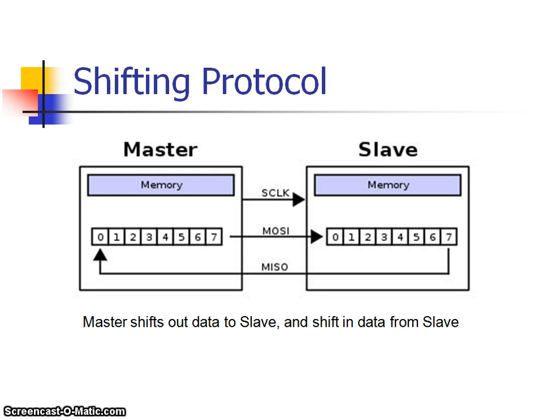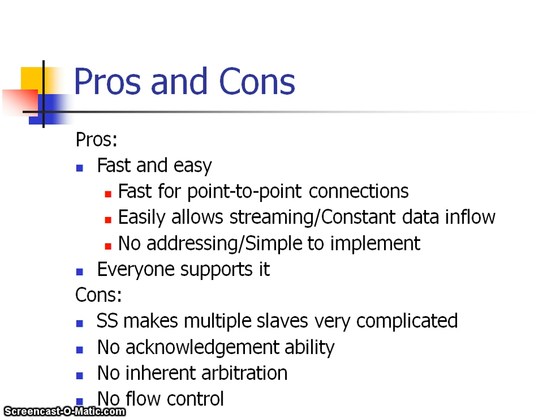The master then transmits the logic 0 for the desired chip over the chip select line. Logic 0 is transmitted because the chip select line is active low, meaning its output is a logic 1 and it is asserted with a logic 0. If a waiting period is required, then the master must wait for at least that period of time before starting to issue clock cycles.